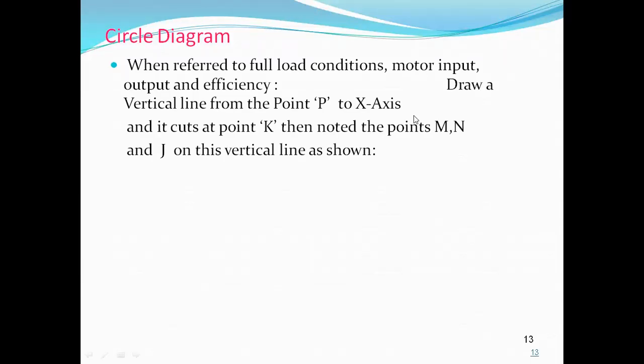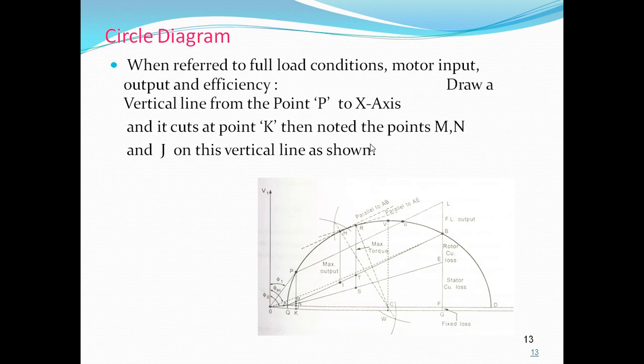When referred to full load condition, for the motor input, output, and efficiency, draw a vertical line from point P to the x-axis, and it cuts at point K. Then note the points M, N, J on the vertical line PK.